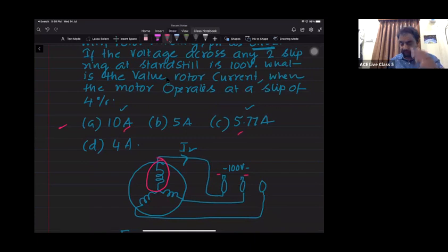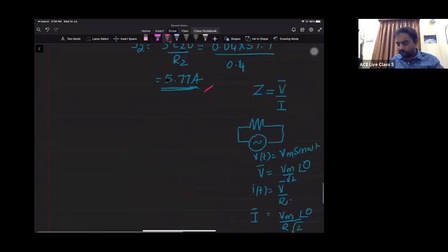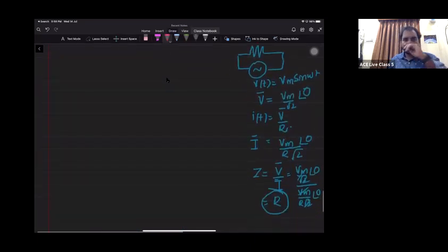Right, done. So this is one analysis. Please remember in all our calculations, whenever the terminology three-phase is given, the given voltage will be a line voltage, but line voltage is a joker. In all our numericals, we need a phase voltage.